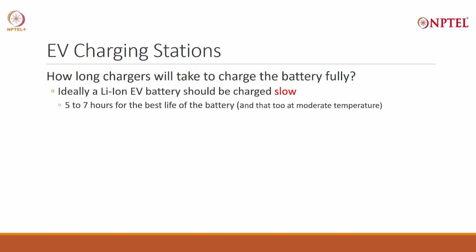Ideally, slow charge is best. 5 hours is good, 6 hours is good, 7 hours is even better. That's what increases the life, and if possible at moderate temperature. So if you are at home in the night, your charging is great, temperature is lower. Even in a shopping parking lot, a covered parking lot, temperature is lower, you can charge it slow, less of a problem.